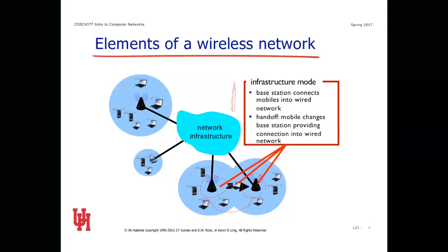Ideally, you have a signal that can be managed by more than one tower, and if that's the case, then they can add other variables into the equation. Variables like the capacity available at the next tower, or the signal to noise ratio at the next tower, or the capacity to backhaul at the next tower, et cetera. Or sometimes they can do it based on whether they're going to have to pay someone, because you may be at the edge of a roaming agreement.